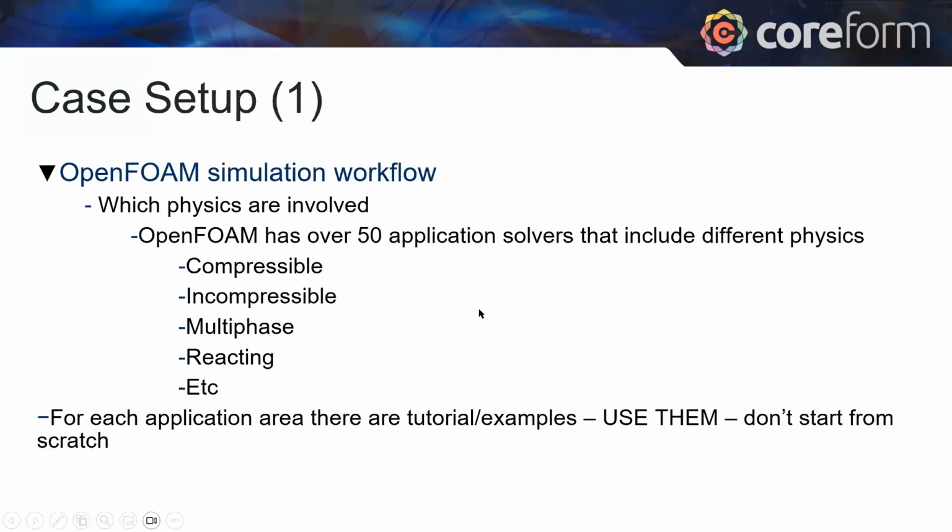Okay, next I wanted to talk to you really quickly about the workflow using OpenFOAM. If you want to do a simulation in OpenFOAM, the very first thing you have to do is figure out what physics are involved in your problem. Like I said, OpenFOAM has over 50 application solvers that include different physics. You can go from compressible flow, incompressible flow, multi-phase flows, reacting flows, etc.